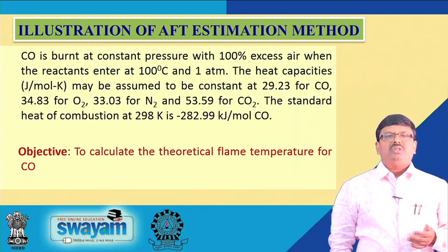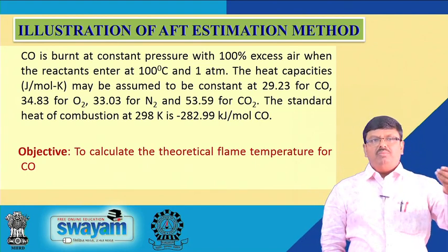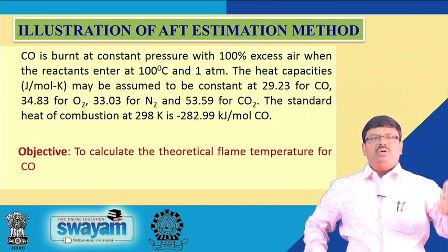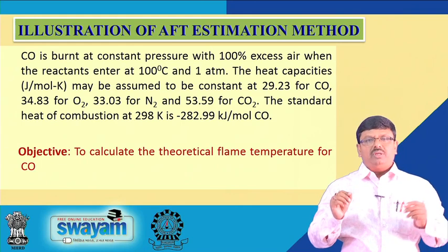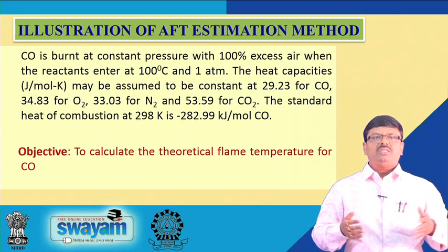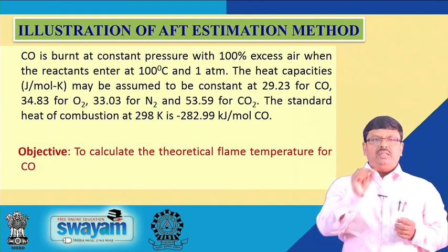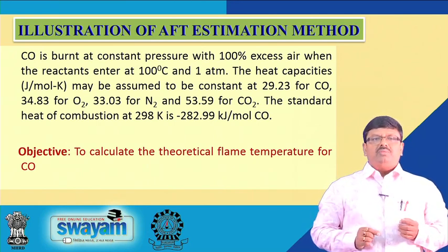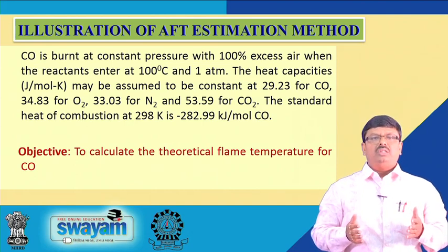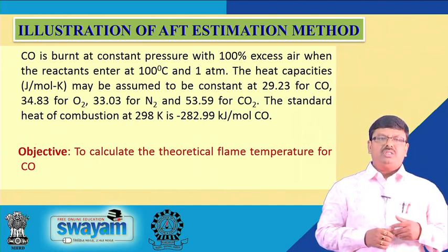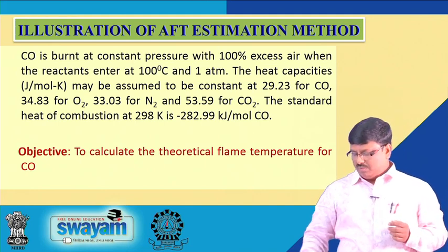Illustration on AFT estimation method. This is nothing but a problem, where we consider carbon monoxide gas supplied to an adiabatic combustion chamber with 100% excess air, when the reactants enter at 100 degrees centigrade and 1 atmosphere. The heat capacities are given and assumed to be constant, and the standard heat of combustion is given. We need to calculate the theoretical flame temperature for this carbon monoxide.